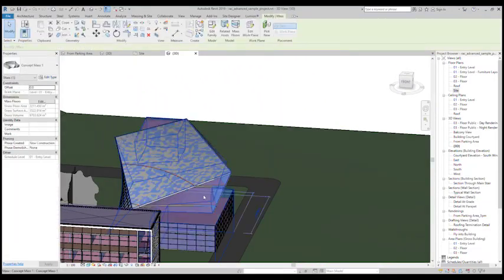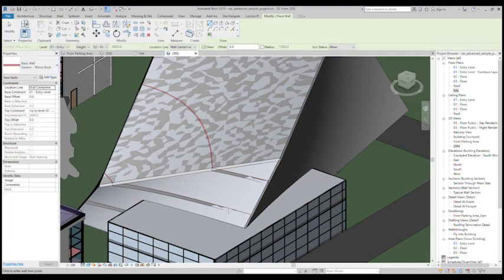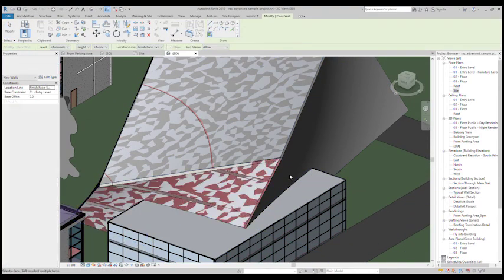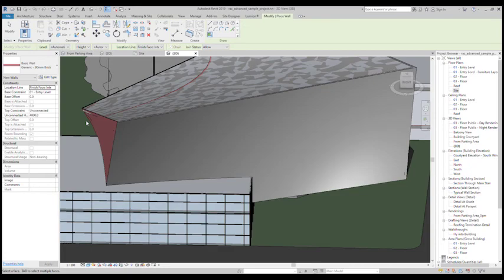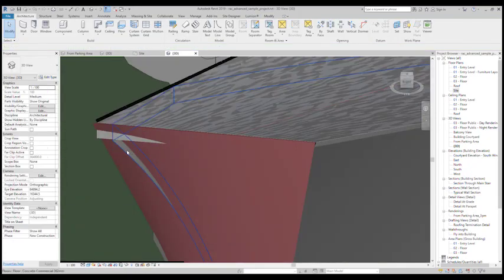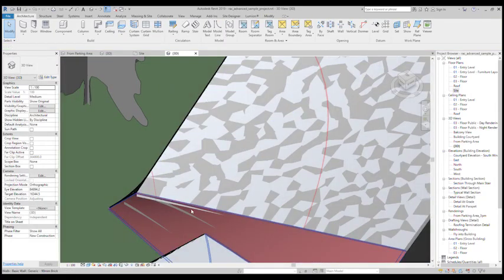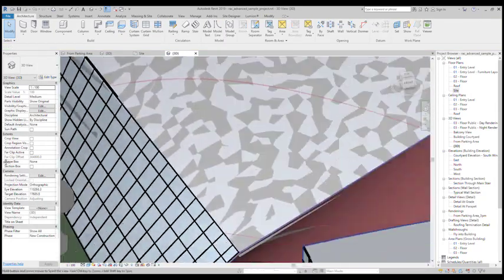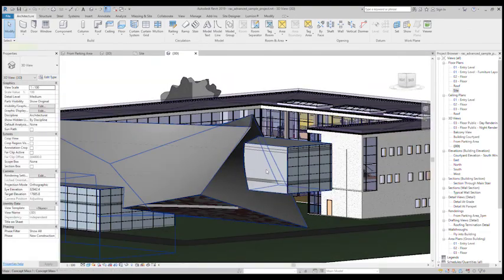I see there's no wall there, so I'm going to place another brick wall on that face. I'm going to shift it to the interior, to sit on the exterior of that face. You guys will always see sometimes, even though you're putting it on the outside, these floors might overshoot and extrude out from your walls. We don't want to see that. Okay, so that's it as far as my building.